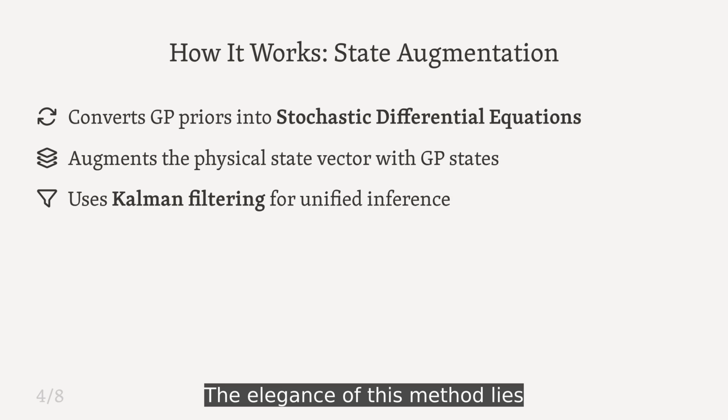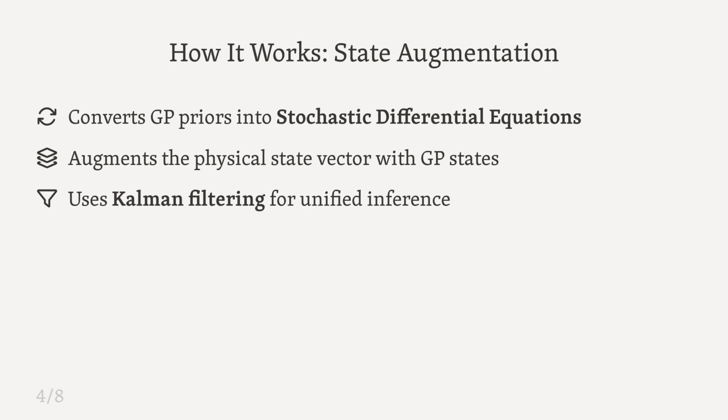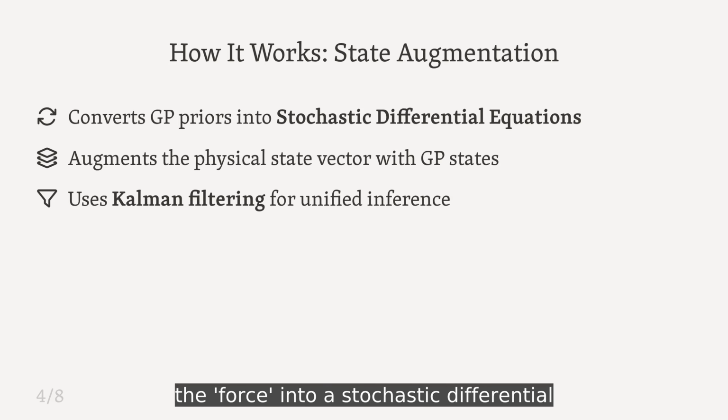The elegance of this method lies in how it handles the math. We convert the statistical prior of the force into a stochastic differential equation, allowing us to stack the force's variables right on top of the physical variables in our system. Once combined, we can use standard tools like Kalman filters to solve for both the system state and the mystery force simultaneously.